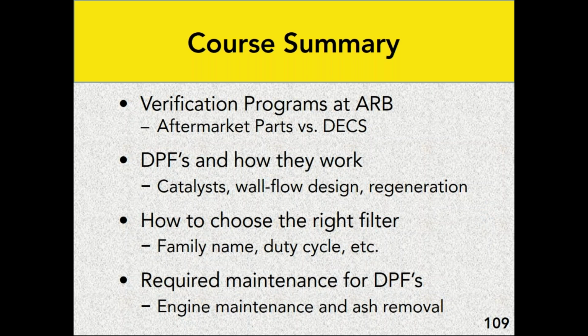All right, we're at the end of the information today. Hopefully I've given you enough information. I've talked to you about the verification and aftermarket parts programs associated with filtration, how these things work, the wall flow design, regeneration. If you're in the market for one, how to pick the right filter, knowing the family name, the duty cycle, and then almost as important as all the rest combined, how you take care of these things once you have one. They're just going to become more prevalent, so you need to understand that the required maintenance is going to be the deal as we go forward.